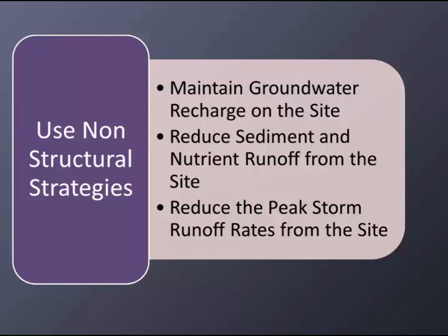Non-structural strategies are used to provide one or more of these objectives: maintain groundwater recharge on the site, reduce sediment and nutrient runoff from the site, reduce the peak storm runoff rates from the site. Using non-structural strategies means not relying on pipes, catch basins, or engineered solutions. They include both environmentally sensitive site design and source controls that prevent pollutants from being placed on the site or from being exposed to stormwater.